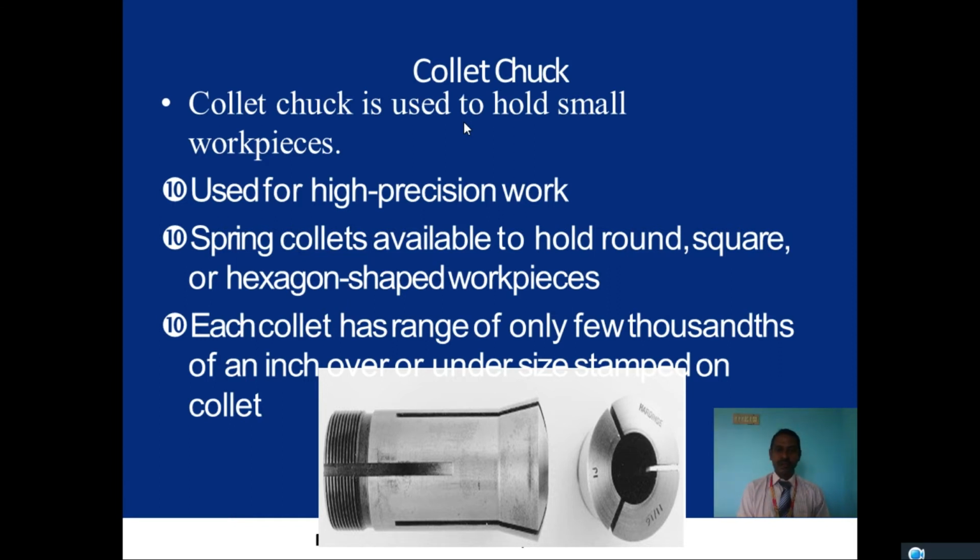Spring collets are available for round, square and hexagonal shapes. Different shapes and sizes are available, and the collet chucks come in different ranges. If it is 10 mm, there is another collet chuck for 10.2 mm, 10.3 mm, 10.5 mm, 10.6, 10.7, 10.8. There are thousands of ranges to hold different sizes of workpieces.